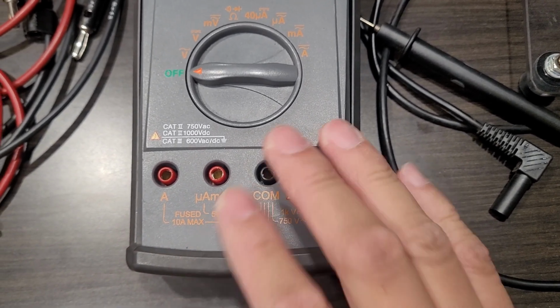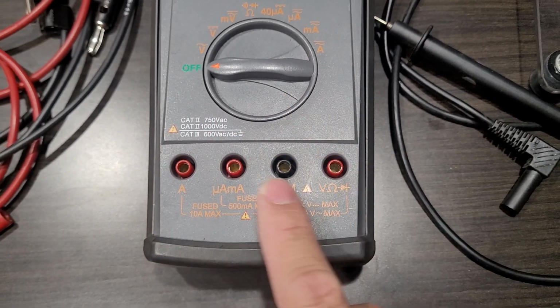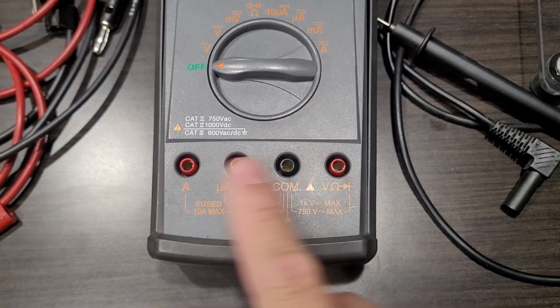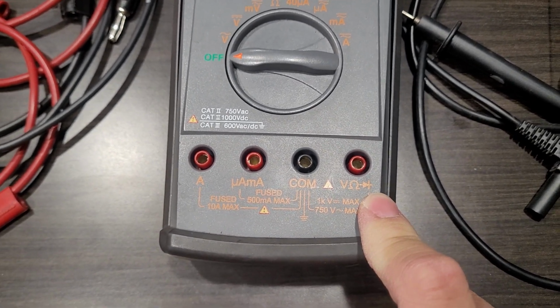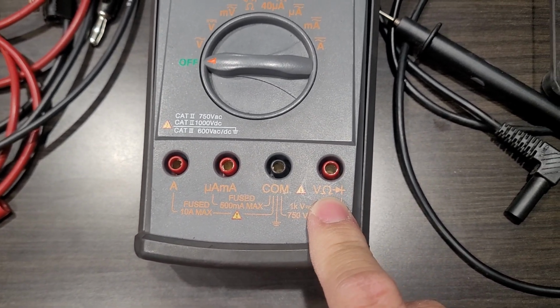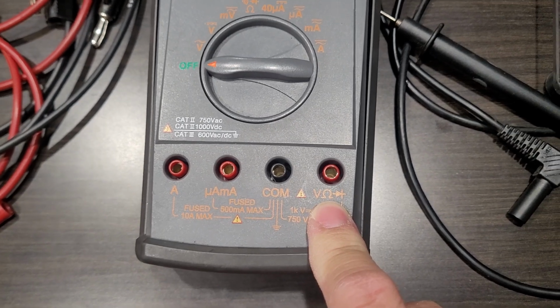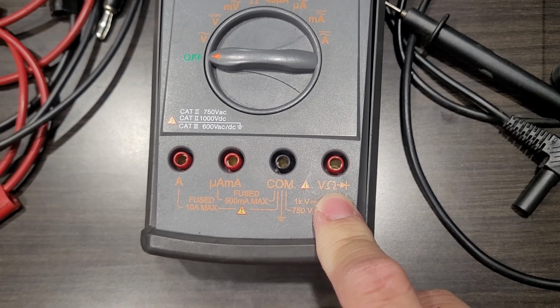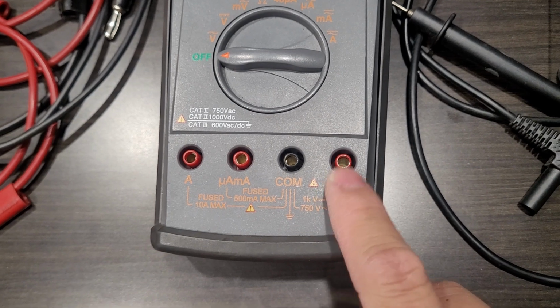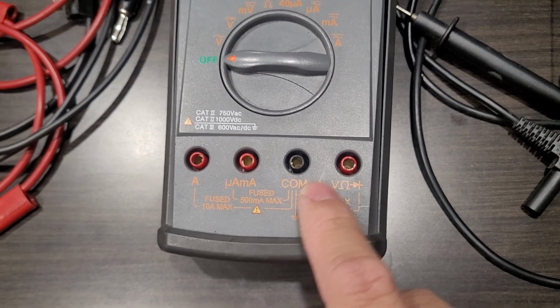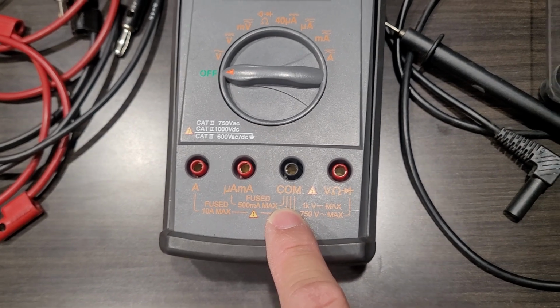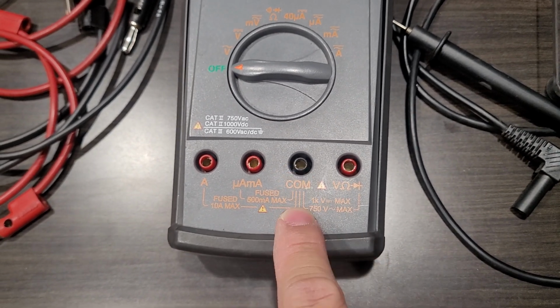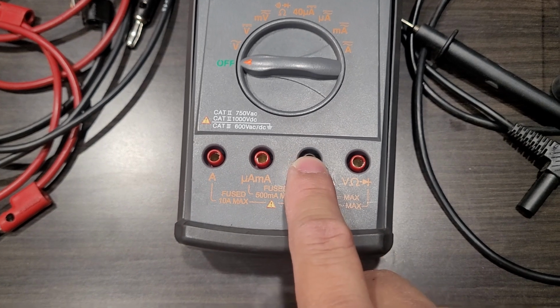Okay, so on some of these, the outlets here might be in a different spot, but again, they will have these markings on here. Now, where my finger is at, I have my voltage, resistance, or diode. So if I do any one of those, I want to make sure I plug it on this side. The COM is usually a fixed spot for your test lead. And again, it's color coded on mine, so I'm usually going to put the black one there.